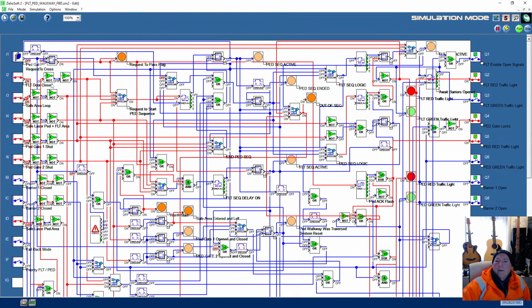Switches over, it flashes the lights. Okay, so yeah. Anyway, so if we come out of sequence, we're in ped gate, somebody opens a door, come out of sequence, it goes into an error state, flashes the lights. All red traffic lights flash every 3 seconds. So that indicates you've got to go over to, so that's the ped gate flashing.